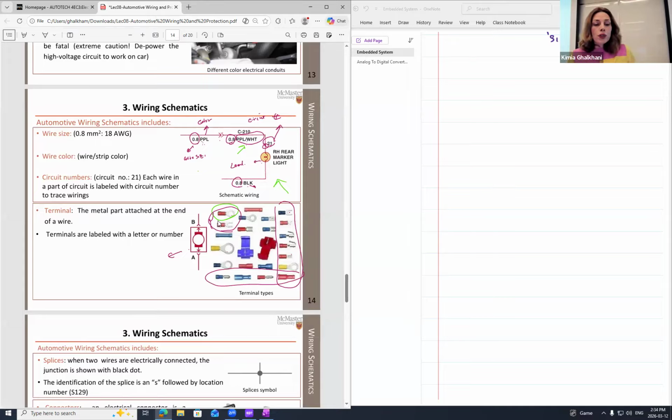But a quick review, you can see right in here in the electrical circuit, when we are focused on wiring, wiring is not something where you just grab a wire and connect it from here to there. Definitely, as I discussed last week, lots of factors are super important in order to have a proper, efficient wiring system. One of them is the length of the wire, and of course the colors don't have a technical impact, but they will have an impact on organizing the system and troubleshooting. But the thickness is also super important.